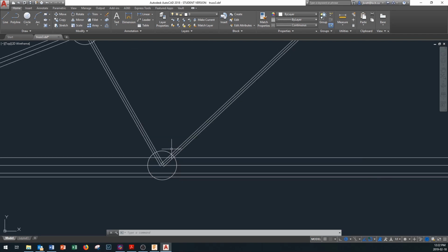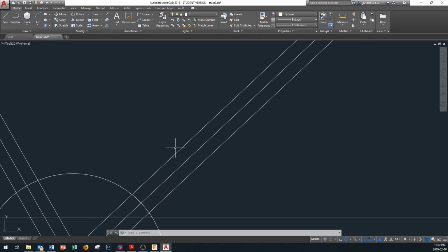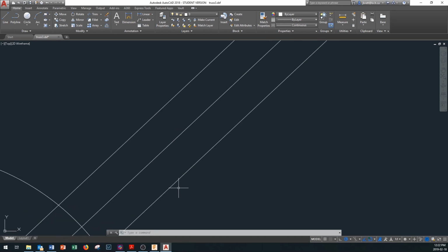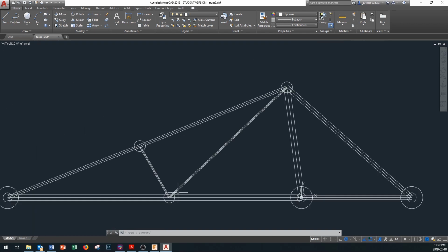Something as simple as the fact that when the laser cuts these narrow members, the laser cuts along this line, and the laser has finite width. The kerf on the laser is about 0.5 millimeters in diameter where it cuts through. So your members are going to come through slightly narrower. And, again, your material may be slightly different and definitely less perfect than the mathematically perfect material used in the calculations in Fusion 360.